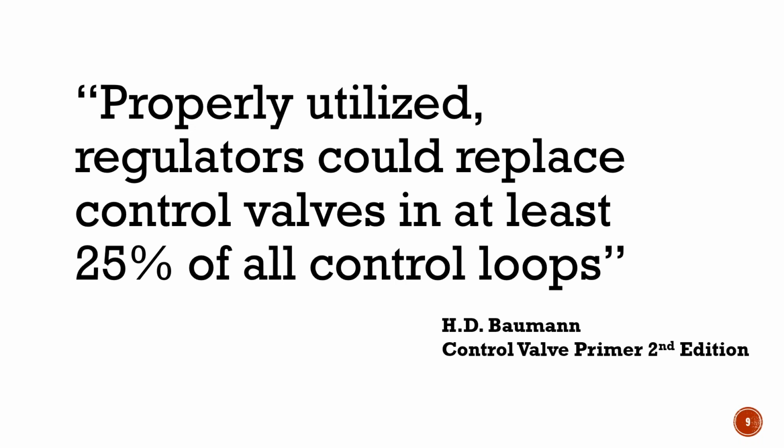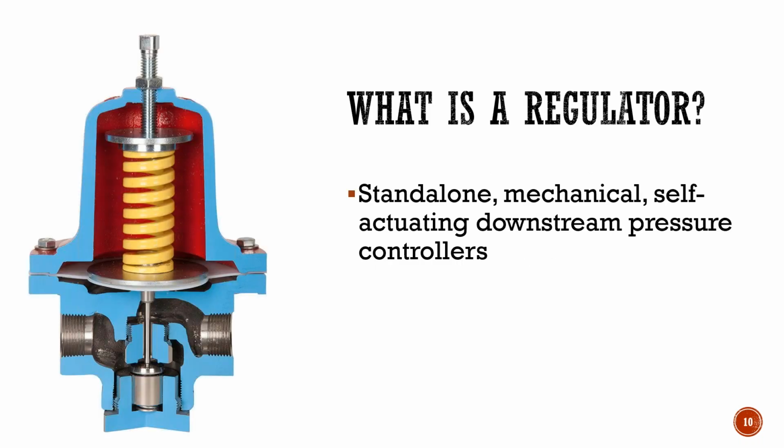So Hans Baumann is, like I say, a big time control valve guy, but he's saying that if you properly apply a regulator, a lot of times it can work as well for you and be a more economical choice than choosing a control valve. So what's a regulator? A regulator is a standalone mechanical self-actuating pressure controller.